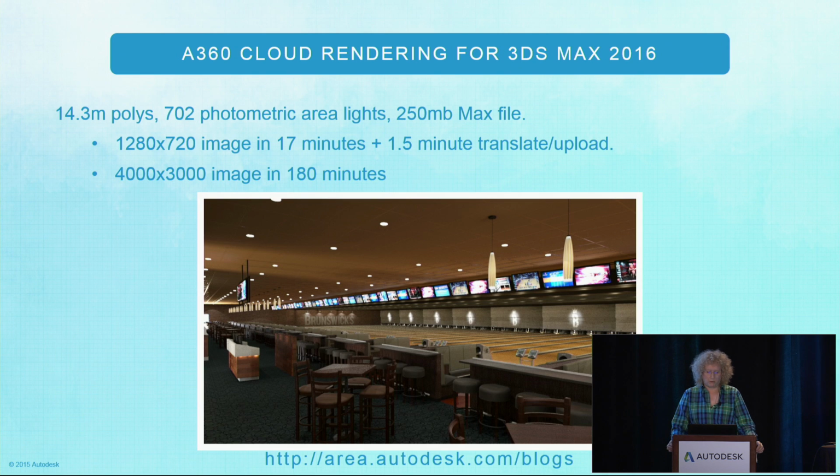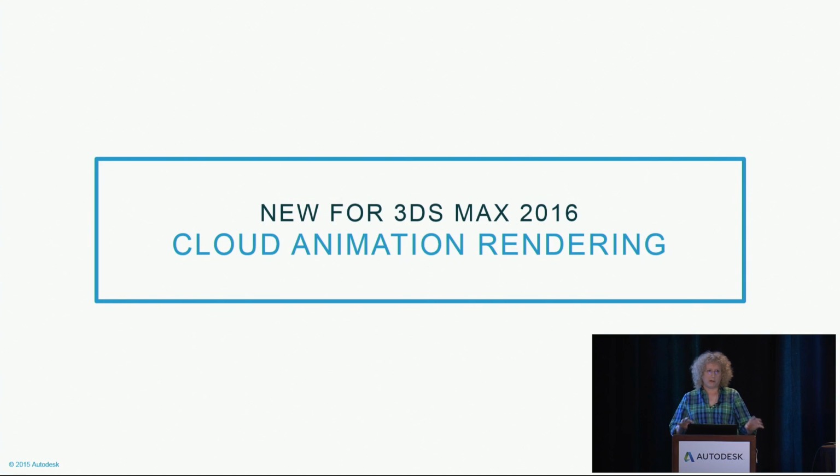On my little home i7 machine and my broadband internet, it only took 1.5 minutes to process the scene and upload it to the cloud. So with a small image, in under 20 minutes, I could have had all of my different cameras rendered, including sending it to the cloud. And even large images, so 4,000 by 3,000, I think is the upper limit, 180 minutes. And again, you could be processing multiple images all at the same time. So lots of advantages to that. If you're doing a mental ray workflow right now, the A360 rendering has a high level of compatibility.